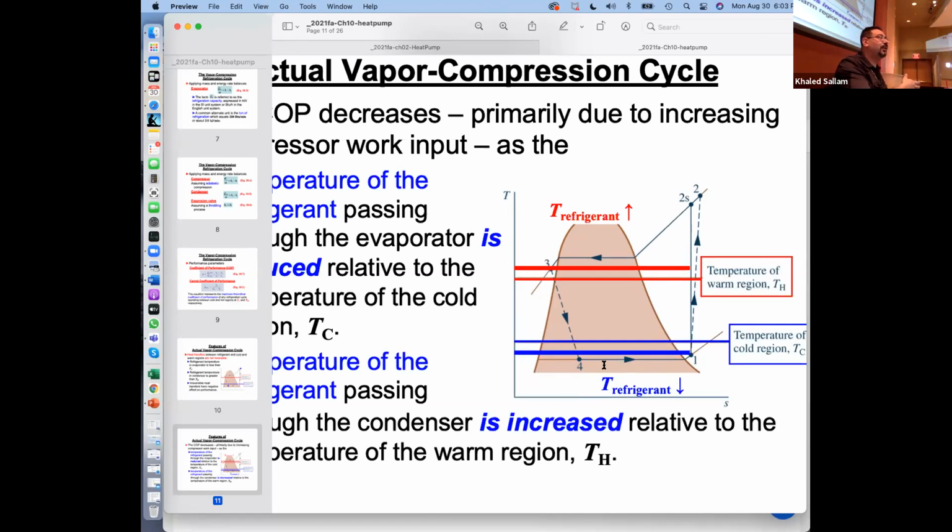And I know that condenser outside is now the evaporator, right? In the winter, this is what's outside, and this is what's inside. So that unit surrounded by snow is trying to do what? Trying to suck heat out of that frozen snow into my house, right?